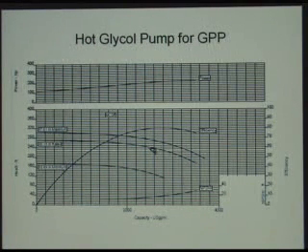Also, if it turns out that something happened with the calculations when they made the initial selection and it turns out that the impeller doesn't generate head as well as it can, they can, by putting in just a larger impeller, go ahead and meet our process requirements without having to go out and build a brand new pump, which would have to physically be larger and then wouldn't fit inside the footprint or the piping spacing that we had set up.